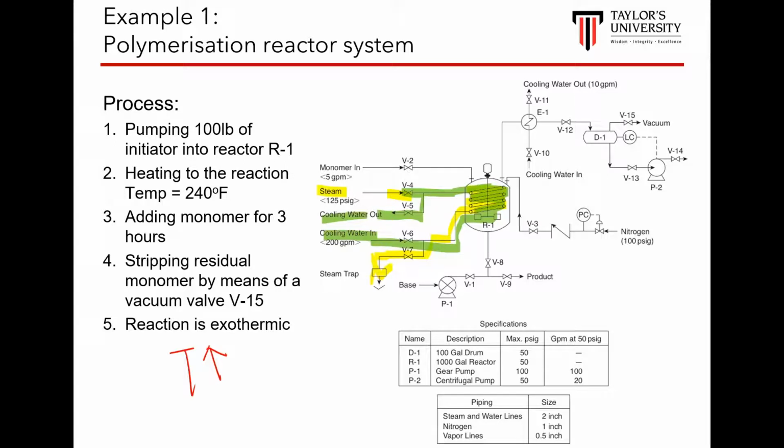Okay, so temperatures then go up when the reaction starts. Immediately when temperatures go up, this valve here will close. So you can see over here, this valve will close, this out valve will close, and what will open is the cooling water, which will then go into the same line and come out using the same system.